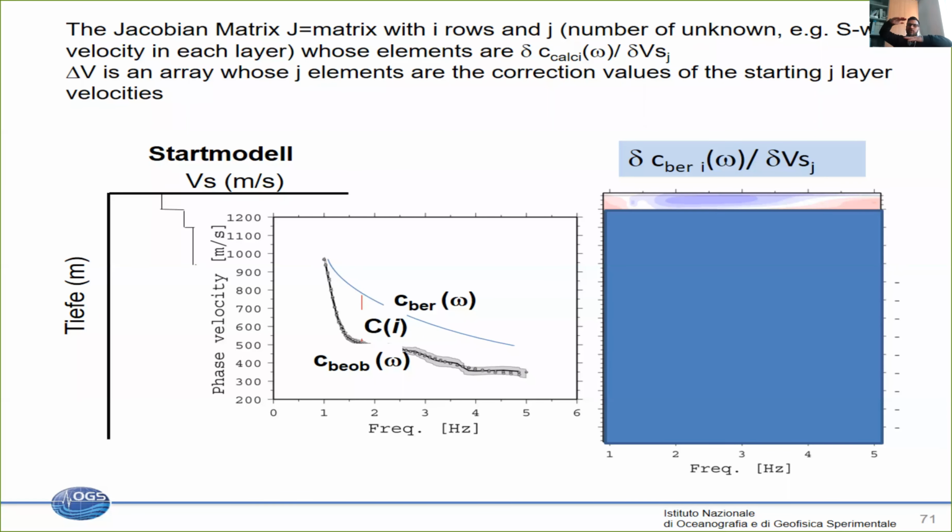So in general, this signal will propagate, since we said lambda divided by 2, in the uppermost 30 meters. So I would say that it makes no sense to have layers thinner than 30 meters in your inversion, because your wavelength is not able to discriminate the velocity changes within these 30 meters. It just sees everything like a sort of average velocity. Okay?